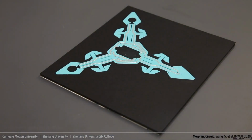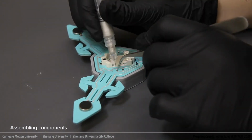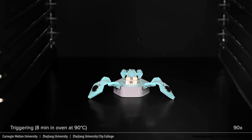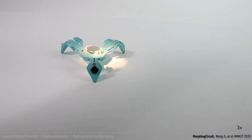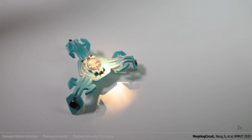We designed sinks on the substrate for electronic components to settle in. After assembly, we applied extra silver ink to the connection points. Then, we put the whole piece in the oven for triggering and silver ink curing. This is a light-chasing robot with integrated surface mount photodiodes, transistors, vibration motors, and a battery. When light is shining, the robot will move to the path of light.